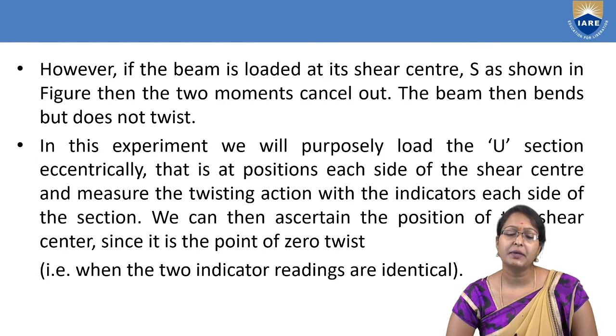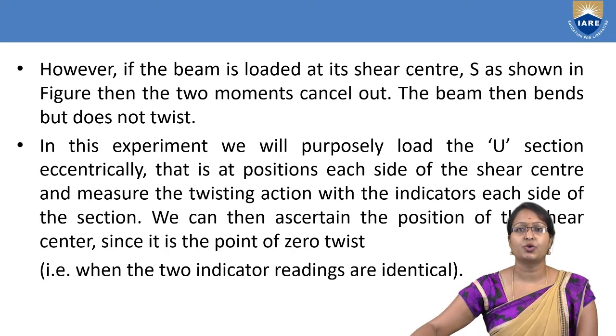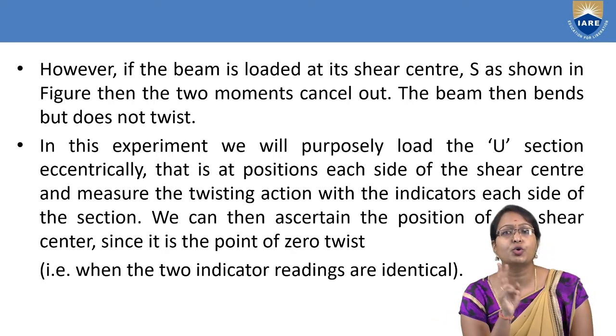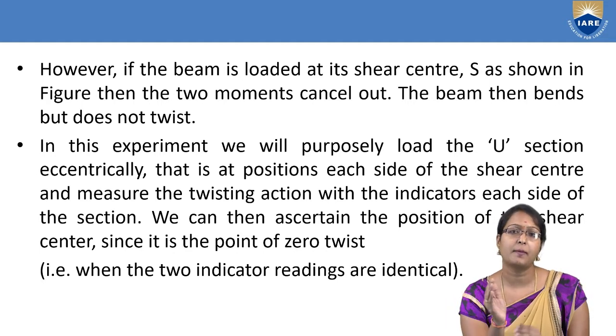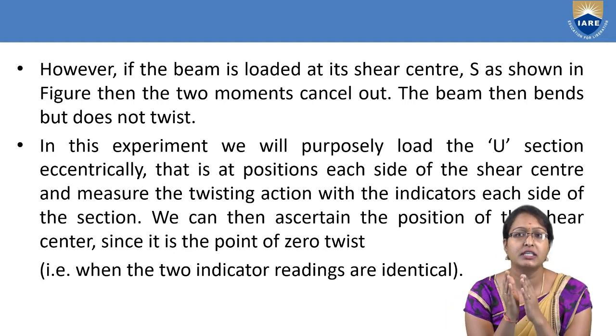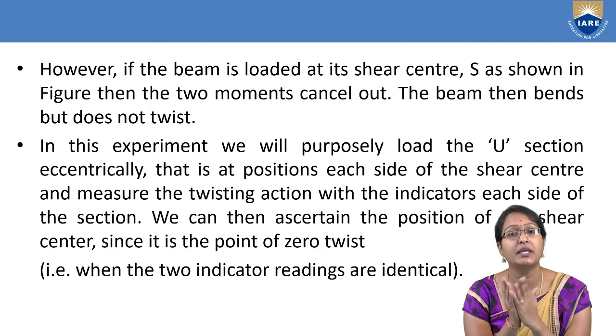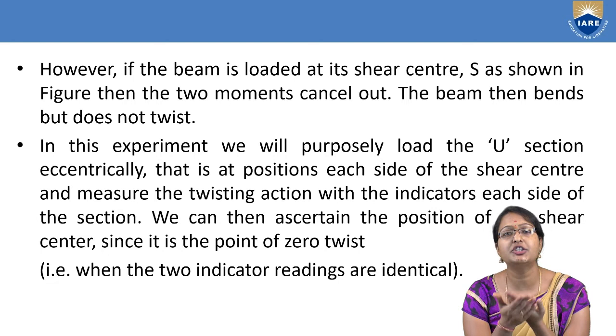However, if the beam is loaded at its shear center S as shown in the figure, then the two moments cancel out. The beam then bends but does not twist. So this is a particular point where the beam bends but does not twist. There we will get the shear center.